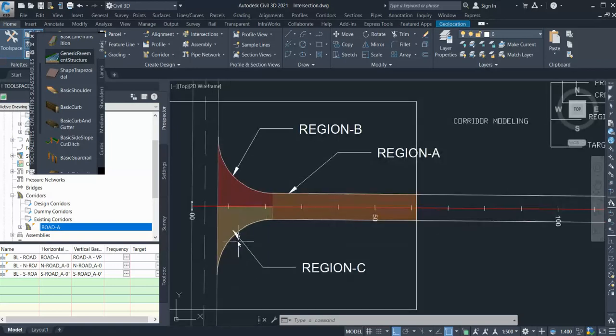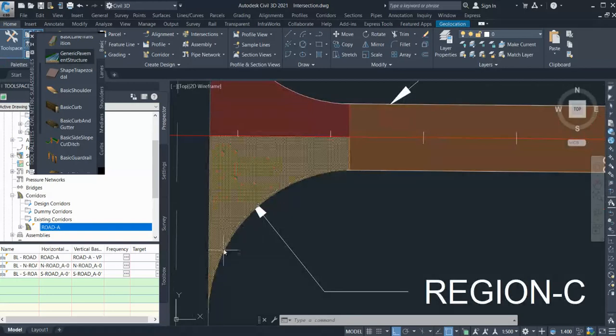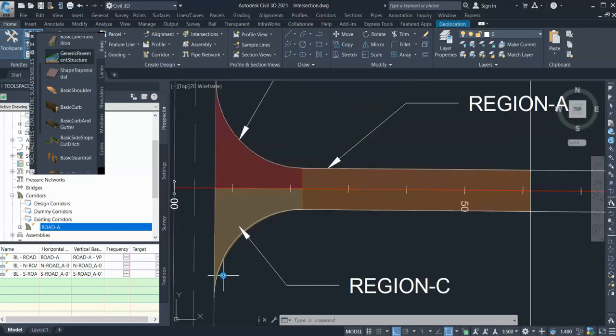The target is needed whenever something is varying. Traditionally the lane width is 3.65, but in some cases you don't have a 3.65 lane. Like in this case, if I have to model this section, my lane width keeps varying: here it will be 1.2, then 1.5, then 2 at its maximum, then lower again. So in this situation you always have to use a target where you have a varying width and varying elevation, because the elevation on the existing would be different from the elevation on the proposed. In that case, you always have to use the target to model this bit of the section.